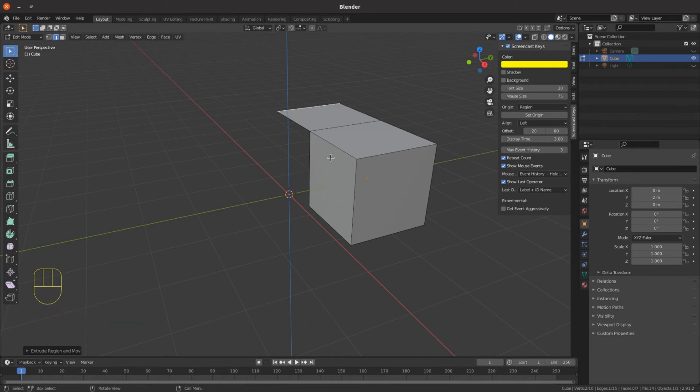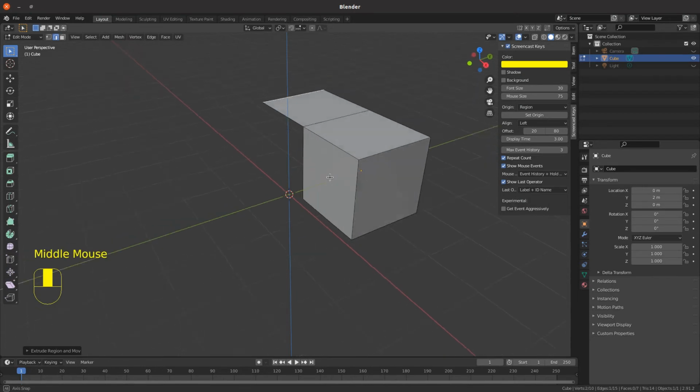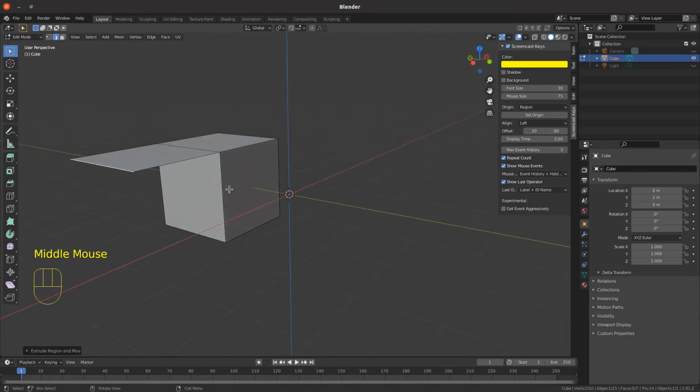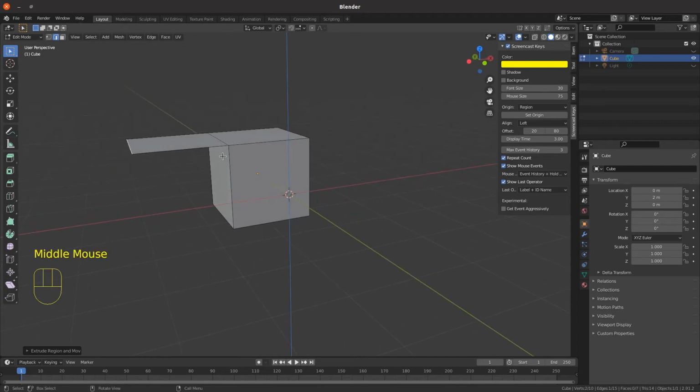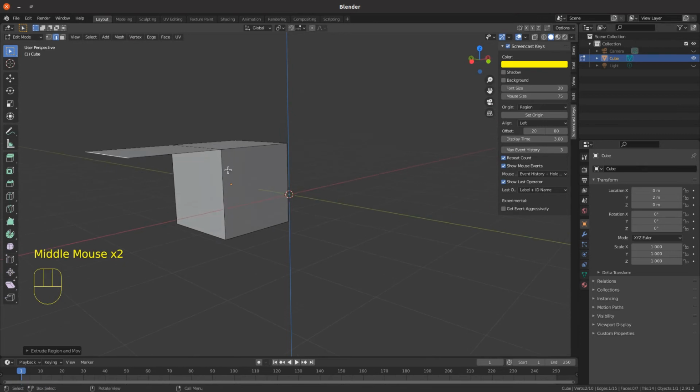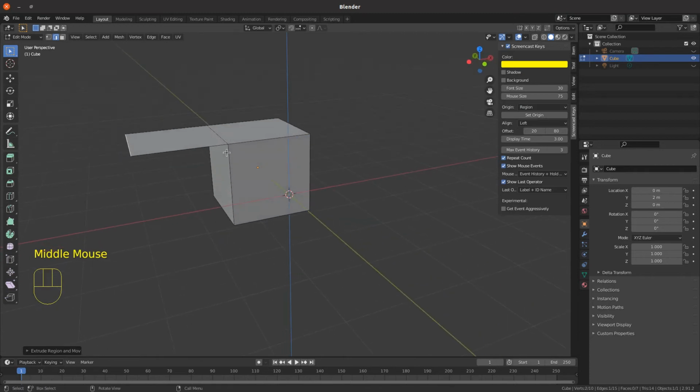So you can gradually build models. This is just using edge select. We'll do face in a minute, but if I rotate the view round, we've got now the cube with one extra face. This brings a shading problem because it's difficult to know which way round the faces are on the cube, which is inside and which is outside on that face.